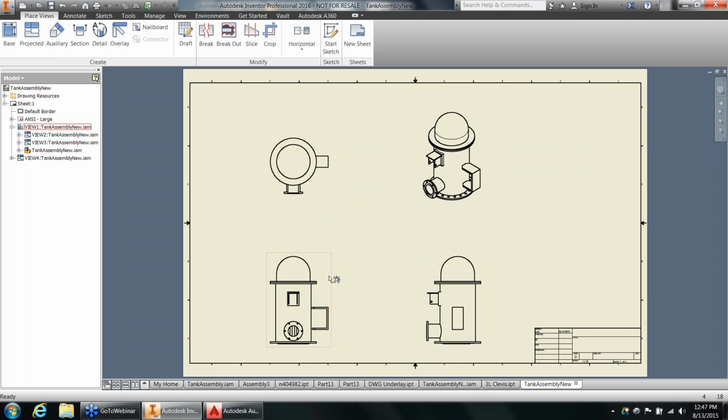in my case, I created a projected part. All I did is I stole a face to make a new face on a new design, so I created an adaptive design. Same scenario with anything else. If I were to go into that design and I totally change the shape of that circular face to create that gasket part, it's a complete crapshoot whether or not it's going to work in the future.